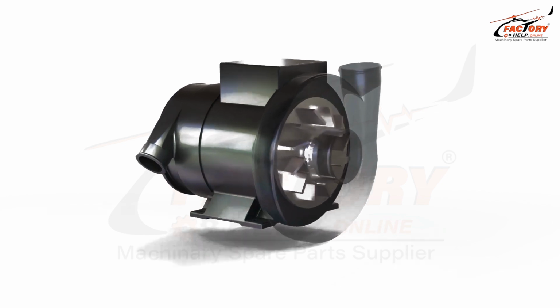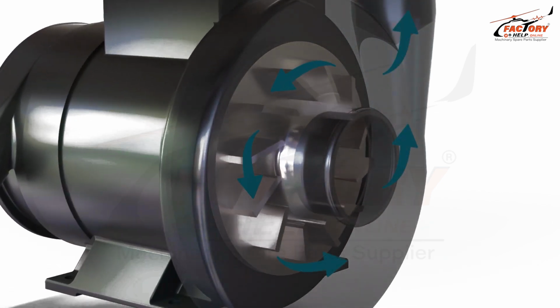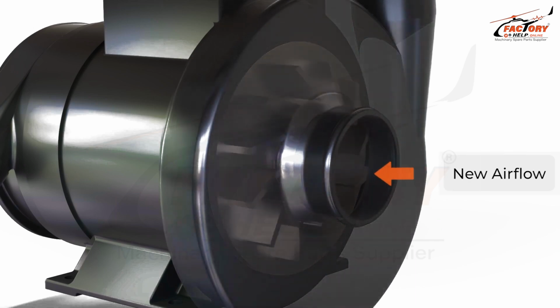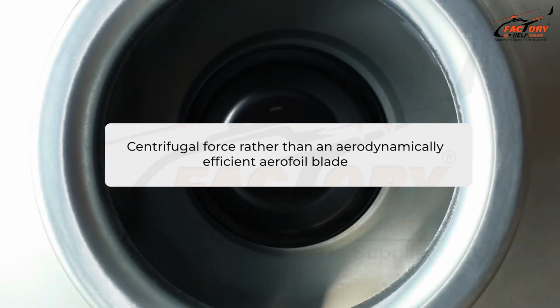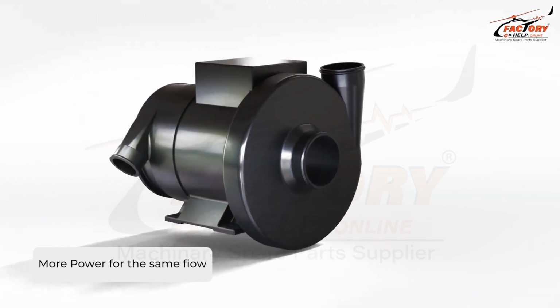For a fan blade, a stall condition occurs when the pressure upstream of the fan becomes equal to the pressure downstream of the fan. High pressure is generated upstream by anything resisting the airflow, including fixed grills, electronic equipment, or variable resistance like a filter that's slowly blocking over time, or passengers opening and closing gaspers in an airplane or car ventilation system.